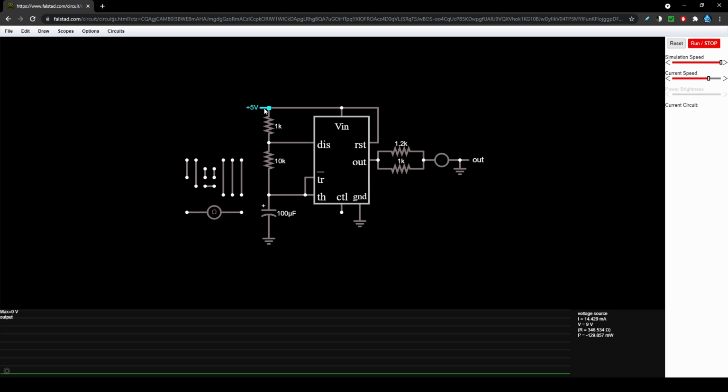As you can see, in this circuit we used 5 volts to create it on here and on the breadboard. You could also use 9 volts, but it will cause a delay in the LED's light. The 5 volt supply goes to pin number 8 in the 555 timer chip, which is the supply voltage for the chip, and also leads to pin 4, which is the reset pin.